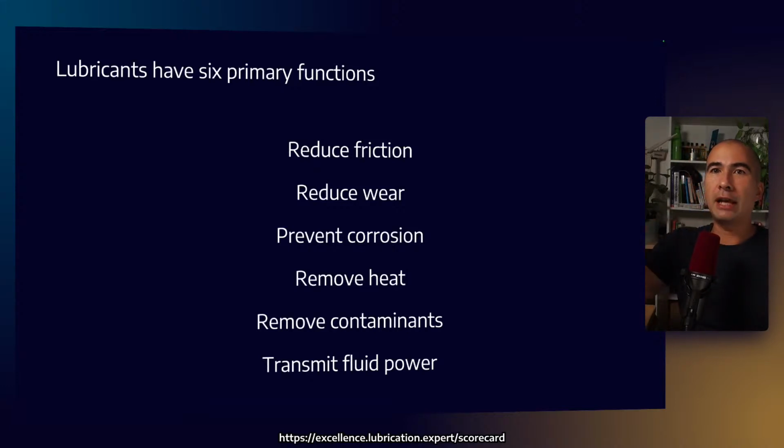Think about an internal combustion engine. The flame temperature, let's say, for example, of natural gas is in the order of 1400 odd degrees Celsius, something like that, that actually exceeds the melting point of aluminium. So if we didn't have cooling oil hitting the underside of the piston crown, those pistons would melt, right? So removing heat is one of the key functions of an oil.